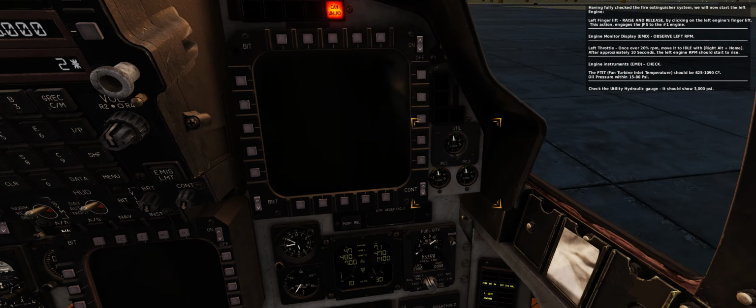The Inertial Navigation System, INS, is a self-contained, fully automatic ring laser gyro system, which supplies the primary attitude reference for the aircraft, and provides continuous present position monitoring. In addition, the INS provides aircraft attitude, heading, velocity, and acceleration information to the HUD, radar, AFCS, and central computer. The INS needs an initial alignment before it can provide accurate navigation.